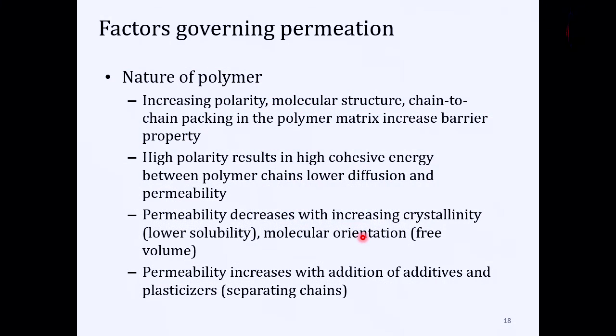But if you have molecular orientation, that is, if you align those chains in a very neat form, then you can also minimize the gas transmission. So the polymeric structure can significantly influence the amount of gases that would transfer through it.